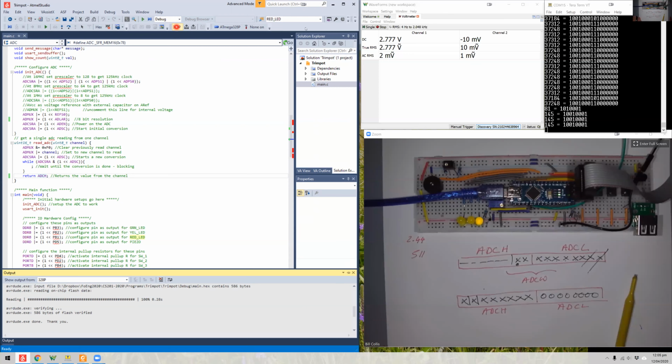Now, actually, I want to just pause this for a second and have a close look at what happened in this line here. This is something that you need to be familiar with. Whenever you're doing your first conversion with an ADC, the first value will generally be wrong. That's when I reprogrammed this, and so instead of reading 145, it read 81. You'll find that the first conversion you do, and the data sheet talks about this, is often wrong, and so you need to ignore it. Okay, I'll just let that go.